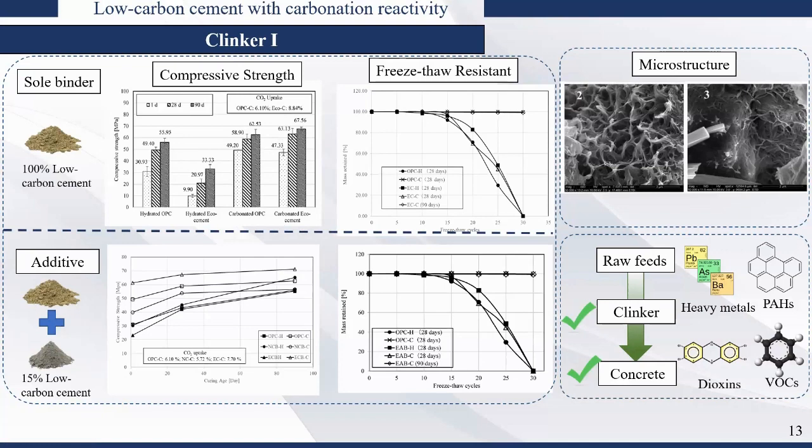And we did a series of durability tests. We want to figure out how it behaves under service life. This is a typical one we chose: freeze-thaw resistance. Freeze-thaw is not a problem in Hong Kong, but since this project was done in Canada, freeze-thaw is a huge problem. We use mass retain to reflect the damage severity of our samples.